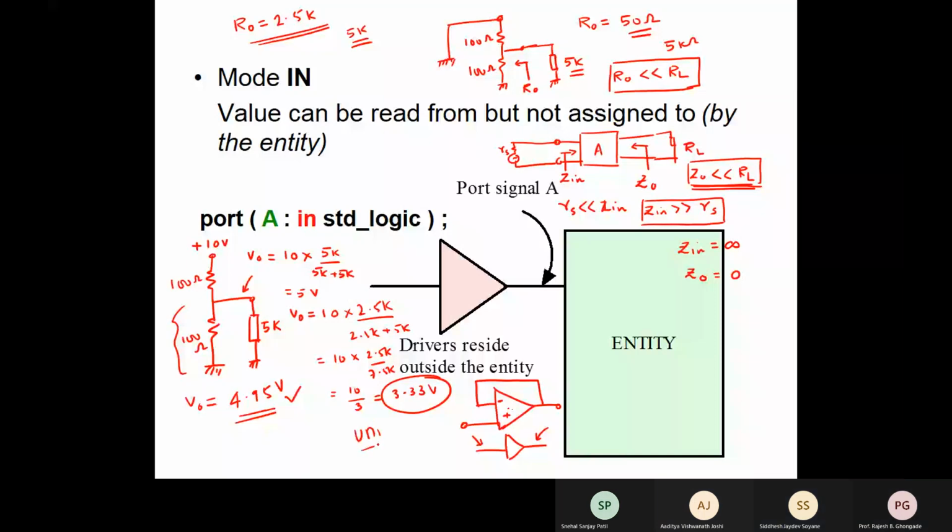Okay? So naturally, when such a kind of buffer, it is also called a driver, is inside the entity, the outside can only read from it. It cannot write anything onto it. See, you will be surprised, but VHDL is not just to be taught like a conventional programming language. You have to have a lot of hardware basics all the way along. That is how VHDL is different from the conventional programming language.